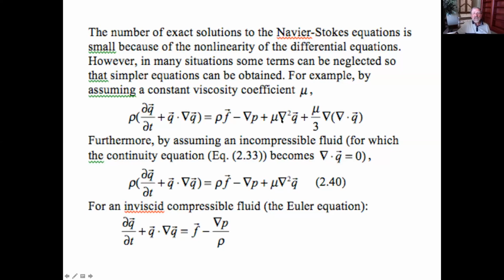So it's the same thing, but with vector algebra, working a little bit and rearranging it. That's the full Navier-Stokes. If I assume incompressible, then this term is actually 0, okay? And then you end up with this equation, which is the incompressible Navier-Stokes. If you assume that the flow is inviscid, so there's no viscosity, okay? Then you end up with this one, which is the Euler equation.